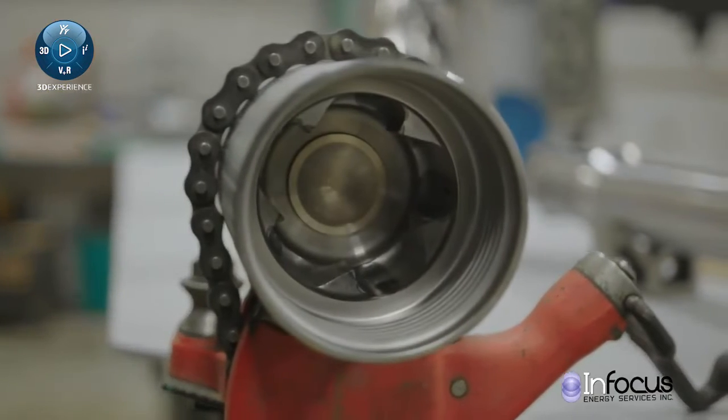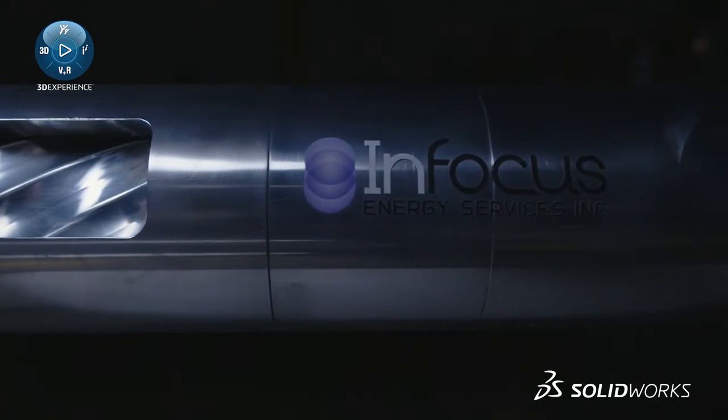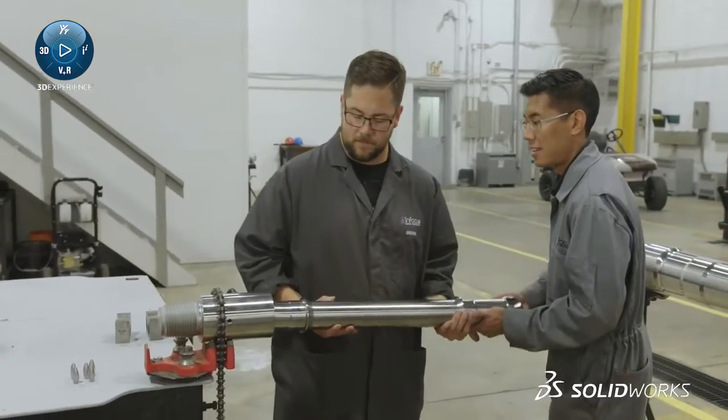As part of the design of our reflex drilling motor, we had to come up with a drive system to transmit about 30,000 foot-pounds of torque through an articulating drive. Traditionally, that would be done with a system using ball bearings. We actually moved to using these custom-designed articulating drive pins. We can get a larger effective radius and a larger effective contact patch out of this design than we can out of this, while still maintaining the articulation.